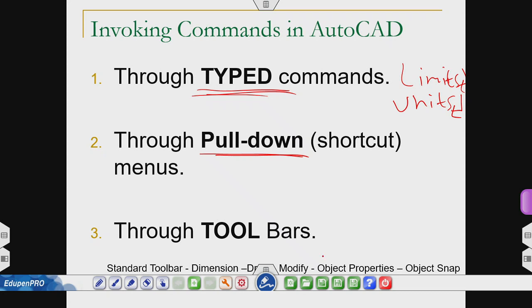It does not always need us to go to the command bar and type whatever command is required. With the pointer, we always have space to write a command. You just directly start typing, and it will start writing at the cursor. So this is called pull down command. Don't worry about it. We will see it when we enter the practical.